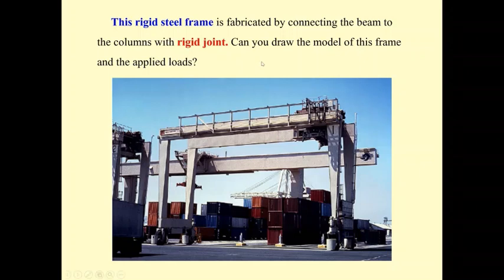Can you draw the model of this frame and apply the force onto this frame? Yeah, usually if this is a pin, you just make it like a pin, and then you attach this pin to the support. Okay, and then for a statically determinate frame, you model this one as the roller, and support it on the floor here.